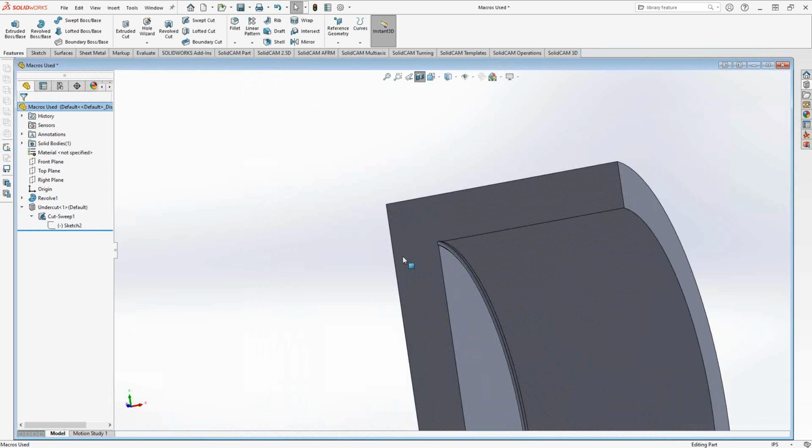This is both for turning parts and milling parts. Basically, this is just a SolidWorks function that you can utilize for any repeating feature that you find that you're constantly adding. Bolt holes, chamfers, pretty much any kind of feature that you find that you're constantly repeating. As long as you can set up your sketching, set up your features with kind of a variability in there, then you can just drag and drop and use it on your parts.